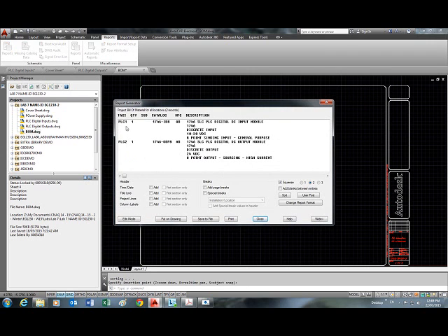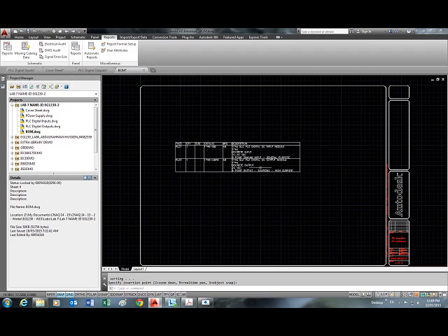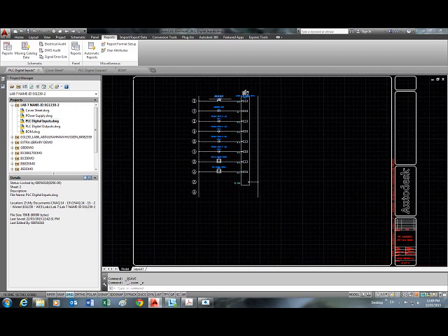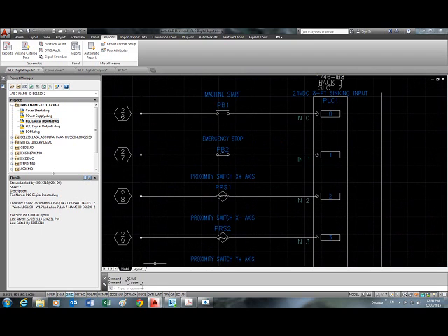and it's showing me only PLC1 and PLC2 because that's all I have defined as far as catalog information is concerned. We'll just say close. Don't worry that it's not complete, because the next time you run the report, you can say update the existing drawing. So we can go to PLC input modules and now start placing the catalog information for these parts.